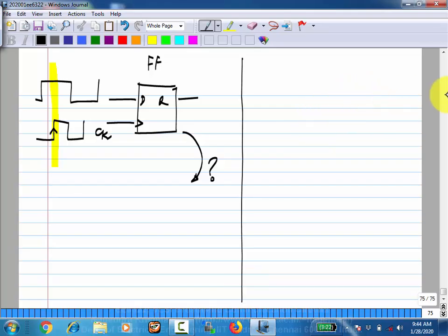So how do you make an amplifier? What is the model for an amplifier that you use? The amplifiers that you know are essentially some voltage controlled current source loaded by a resistor, and there will always be some parasitic capacitor. This is very important because every MOS transistor comes with a parasitic capacitance at its input and its output. Let's now first consider only the output, but it's always like that. Okay. So now the idea is this is the amplifier.